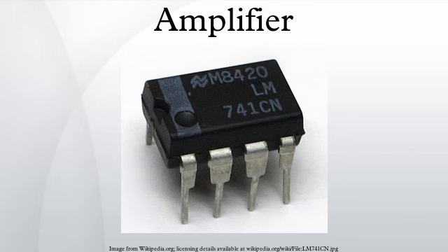Class F, in push-pull amplifiers and in CMOS, the even harmonics of both transistors just cancel. Experiment shows that a square wave can be generated by those amplifiers. Theoretically, square waves consist of odd harmonics only. In a Class D amplifier, the output filter blocks all harmonics. That is, the harmonics see an open load. So even small currents in the harmonics suffice to generate a voltage square wave.